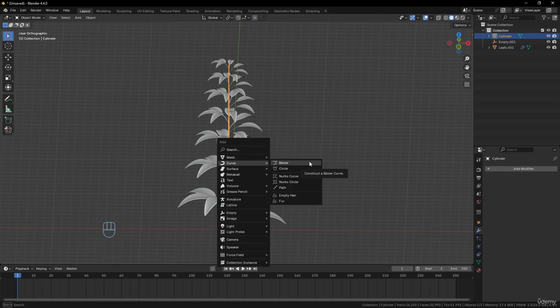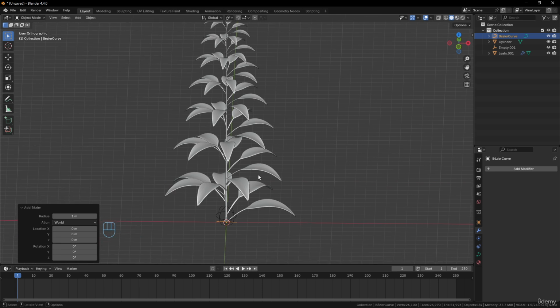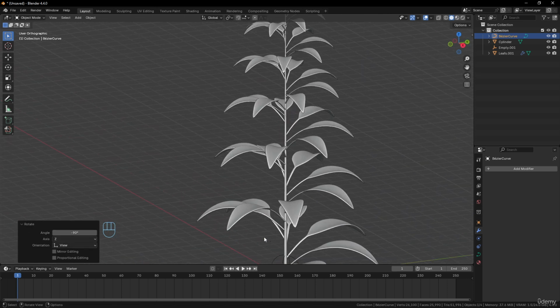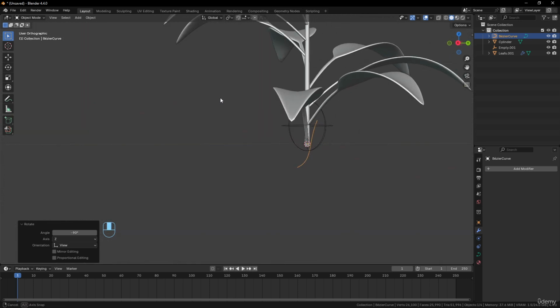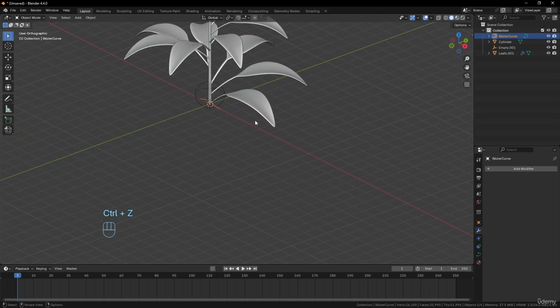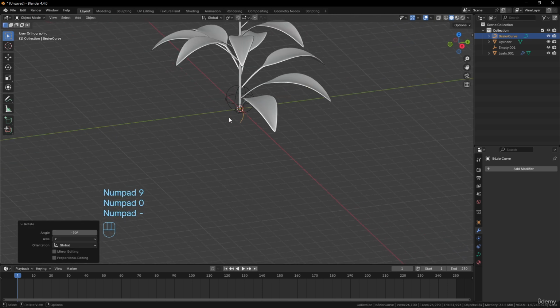Let's add a curve here. It will be maybe a Bezier curve, or a path might work as well. But a Bezier looks good for me. So here I will make a rotation 90 degrees into numpad negative like this, okay, to have something that looks like this. So I come back before, Y 90 degrees minus should work.